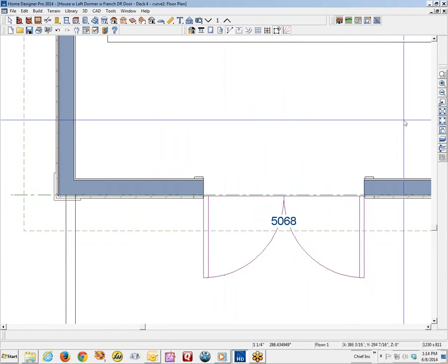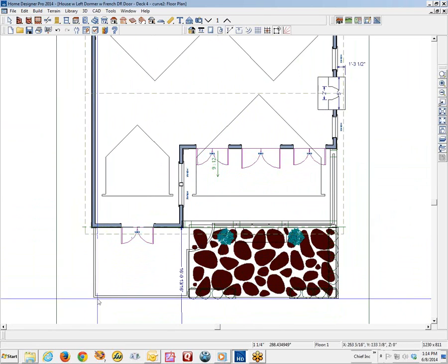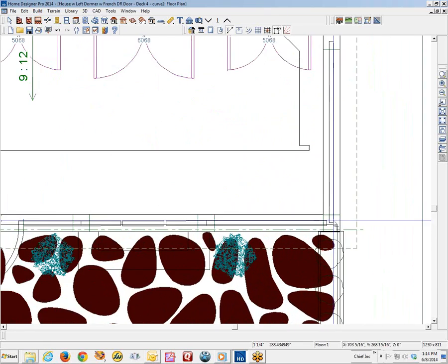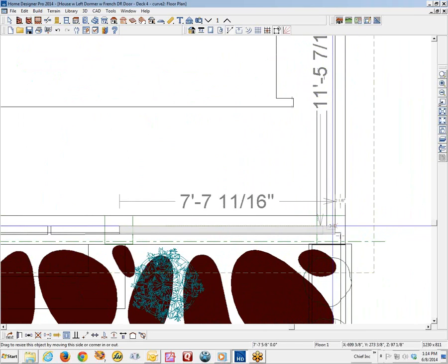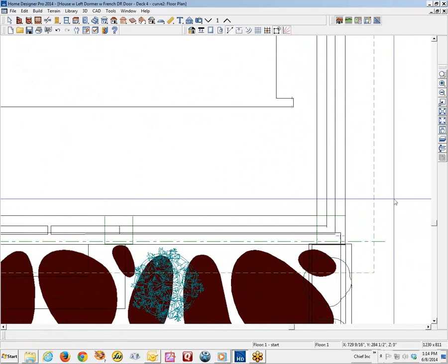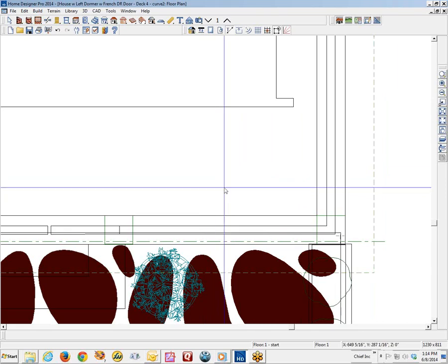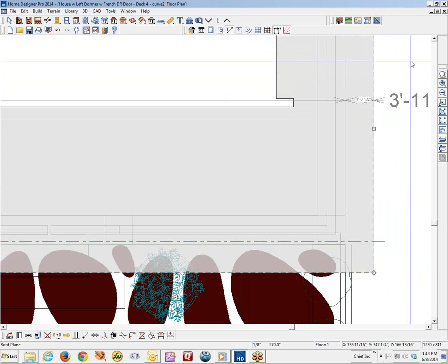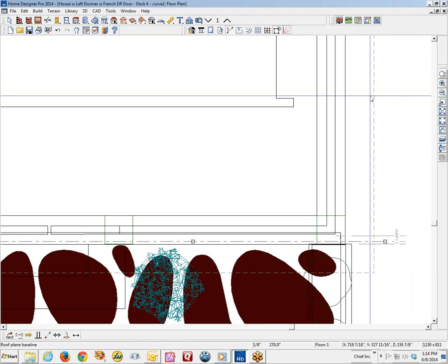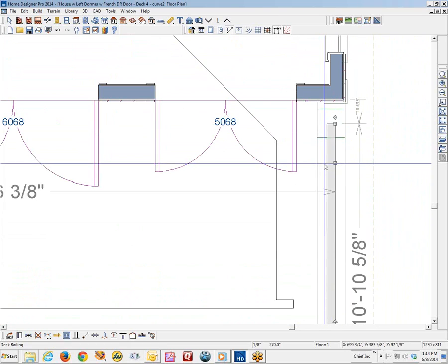Still no dialog box. Okay, so there's some other problem going on. So I'm just going to follow those. Those look like they're connected. That's connected. Okay, right there. No wall, no enclosed space. In other words, when this was enclosed, the decking was automatically built and the decking stayed. But to do anything further, to fill in that spot, we have to find out why this isn't making a room dialog box.